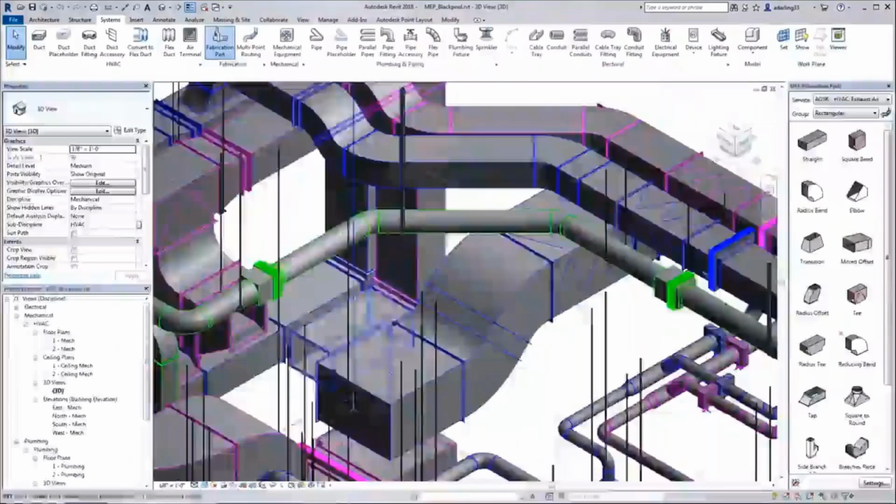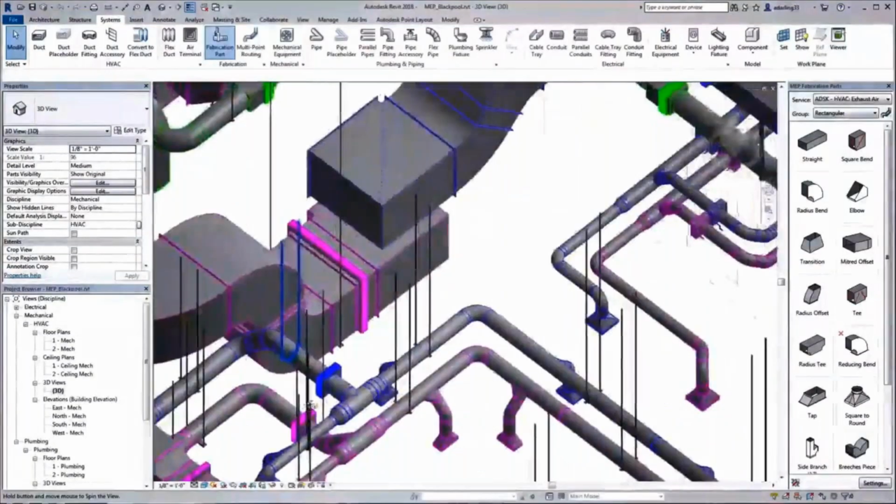And now you might be having some doubt. Maybe once it is converted to fabrication content, will you be able to create some ductwork? Yes, it's possible. You can just select that and you can start creating as fabrication content also. You can just select two different points. You have a route and fill option also. It gives you different ways of connectivity of fittings. You can use it here. It gives you multiple suggestions. You can use whichever is working for you.